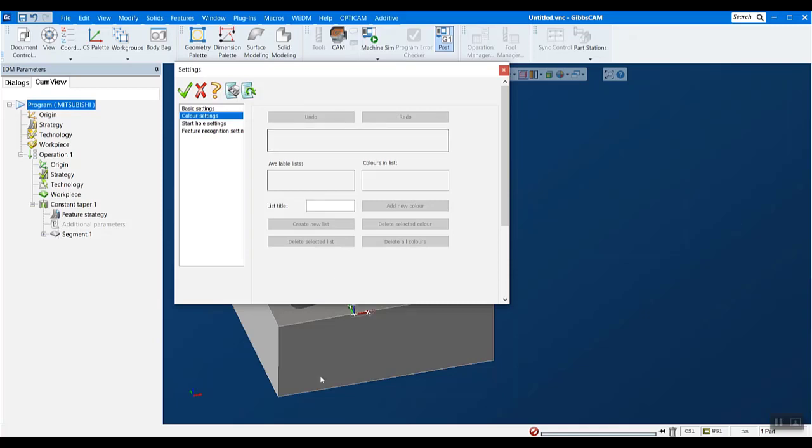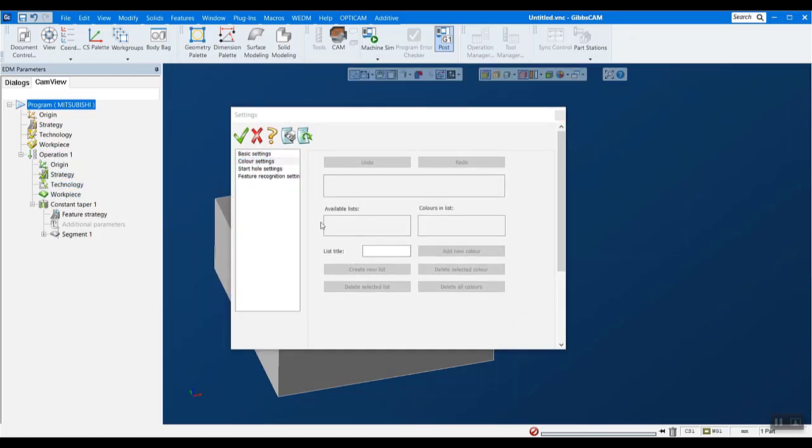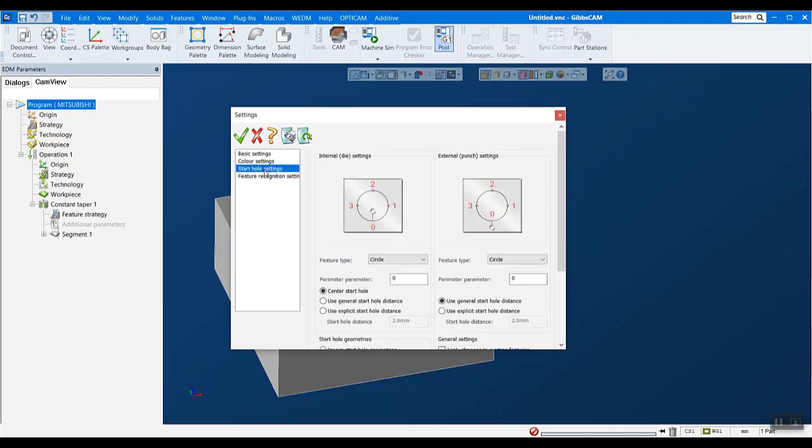And then when we import that into Opticam, it automatically recognizes these colors and will automatically machine those features based upon the color. So you would have maybe a yellow color that represents certain tolerances, where a red color might represent a tighter tolerance, something like that. And all that will be automatically done for the technologies that you specify for each color. So I'm really excited about that. I think that'll help a lot of people out as well.